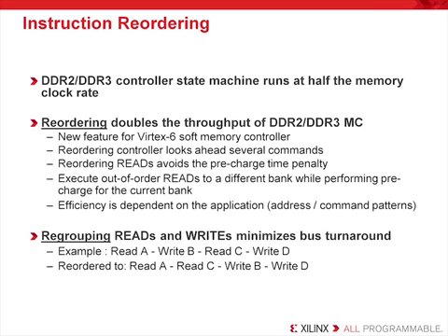In addition, the new controller has the capability to reorder commands for a more effective data bandwidth utilization. This is very important because we cannot afford to simply crank up the clock frequency and get more bandwidth by brute force. In some systems, if the controller is not effectively using the data bus, the actual bandwidth can drop to 10% of the maximum capability.